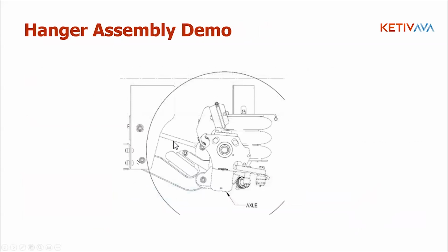Okay, so Jammie, you use design states more as like a manufacturing guide. So we're going to do bend A first, then bend B. Maybe we'll then go put it on and do some punches. It was just mainly for like a guide. Correct. Yeah, you can almost take your manufacturing process as is, whatever your company standard is, and create that in different states and steps within Inventor now using model states.